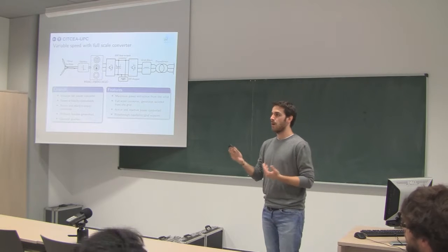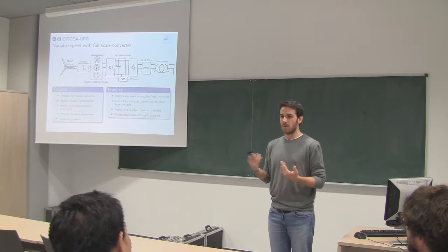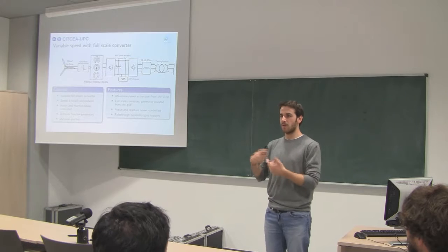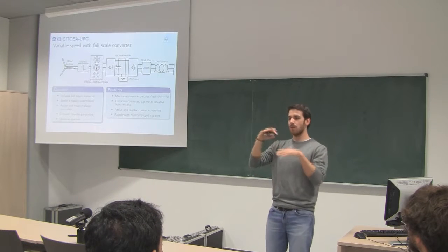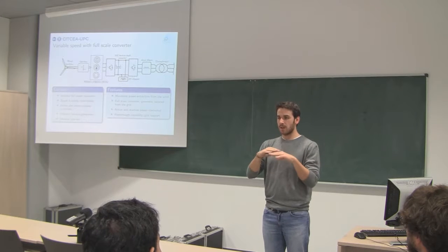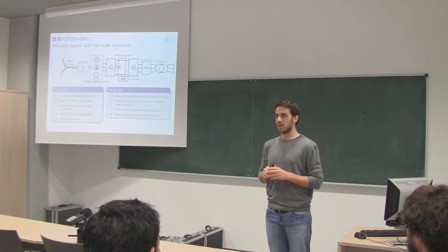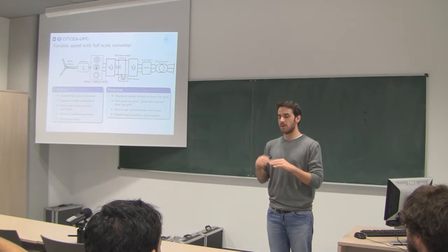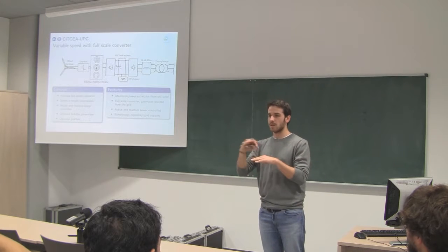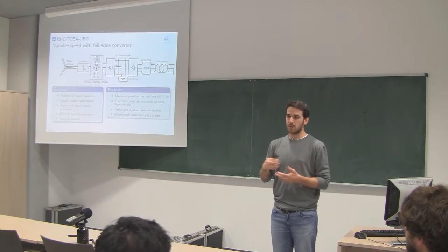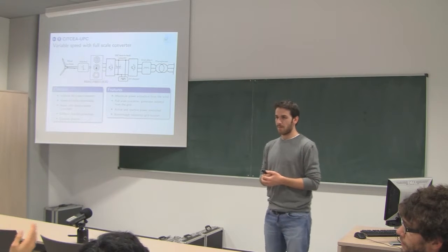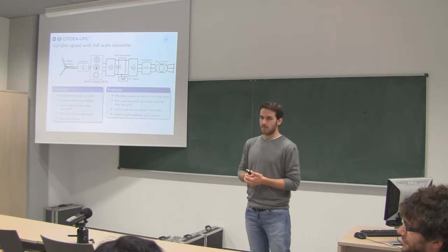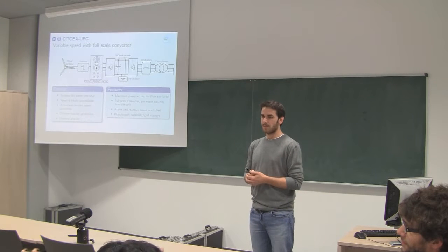Of course, if you have an overrated generator and an overrated converter, you could do that. In some machines, for a few seconds, you can handle it. They are rated for 6 megawatts, you can handle like 7 megawatts transiently, but not in a steady state because they will burn. So this means that even with this configuration with all the power electronics behind, you still have to rotate the blades.